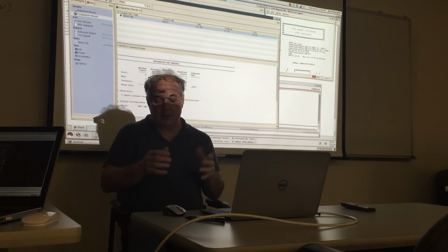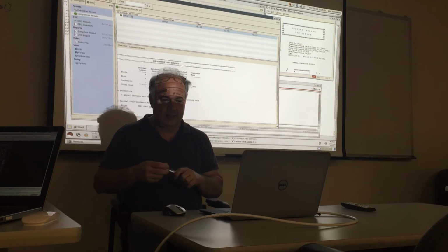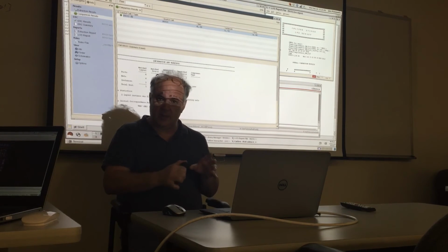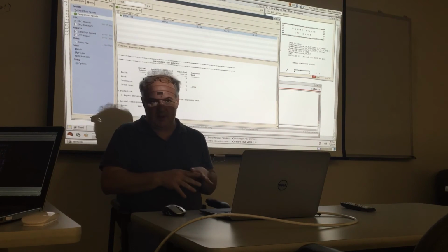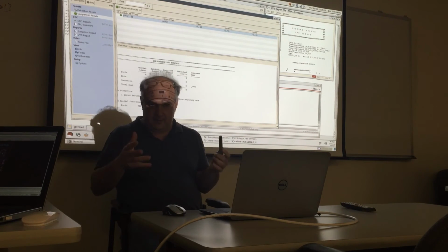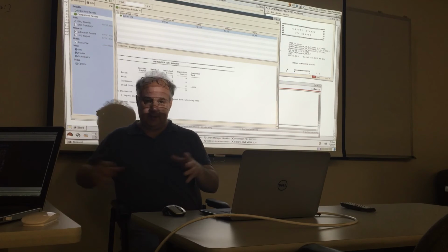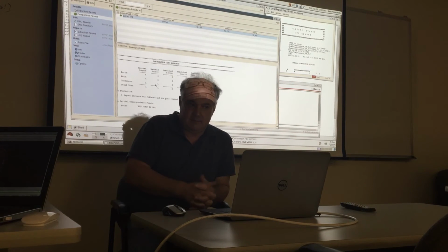The worst case scenarios are the ones where you have macros that have problems, and then they get kind of difficult. But if you do all your standard cells correctly, the tool is responsible for constructing the schematic and the layout for the macros. And if you've done a good job in the standard cell library, I've never had any issues with violations.